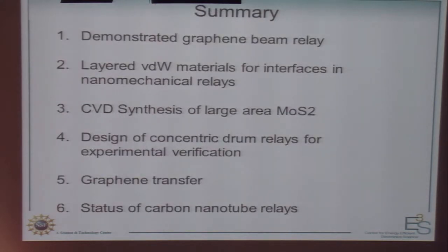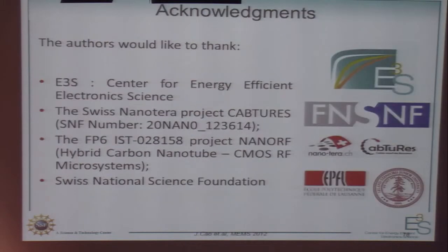So as a summary, I demonstrated a graphene-based beam relay. We showed how layered van der Waals materials can be good interface materials. We looked into the CVD synthesis of large area transition metal dichalcogenide, designed the concentric drum relays for experimental verification. We were focused on graphene transfer and also showed the status of carbon nanotube relays.